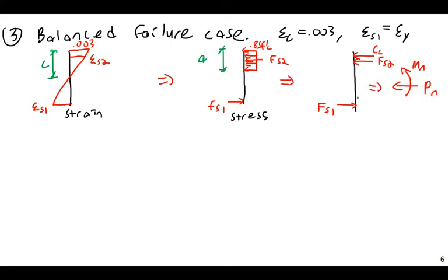So basically the approach is that I am looking at the section. When I'm calculating this interaction diagram, I'm picking a few key points, usually in terms of critical strains or critical stresses, depending on the point. Based upon that, I'm saying, if strain is at this, what kind of stresses do we get?